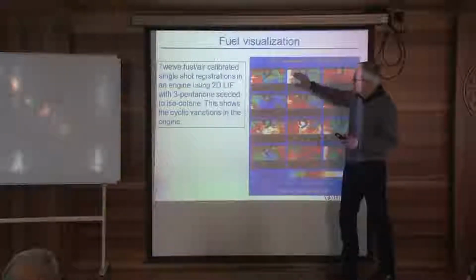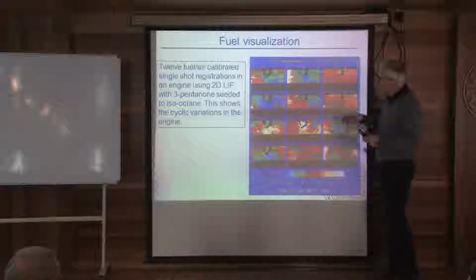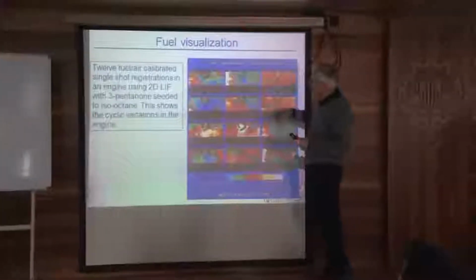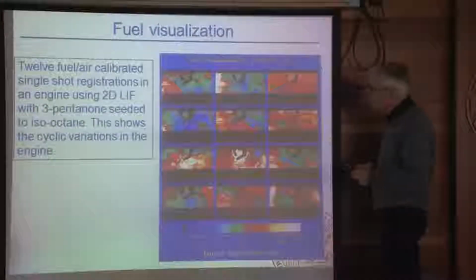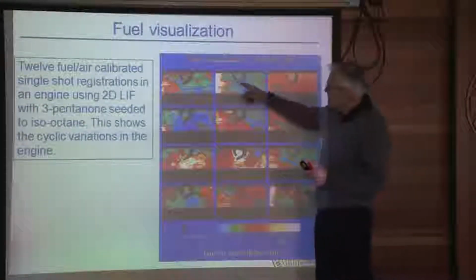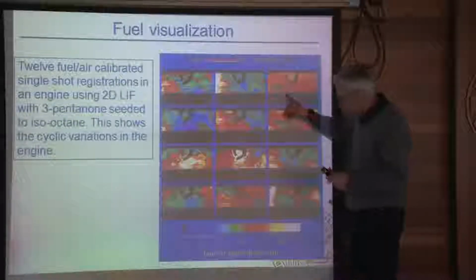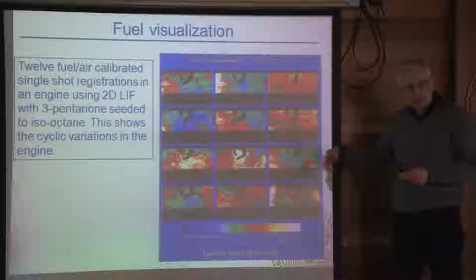And in this case, after all of this fundamental work, this was, by the way, a slightly different setup than what I described previously. This was with the windows at 90 degrees. But here are different individual measurements. Here you can see the spark plug. And the nice thing with this is that the air-fuel ratio could be estimated.